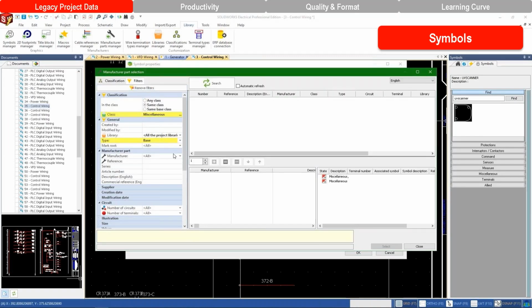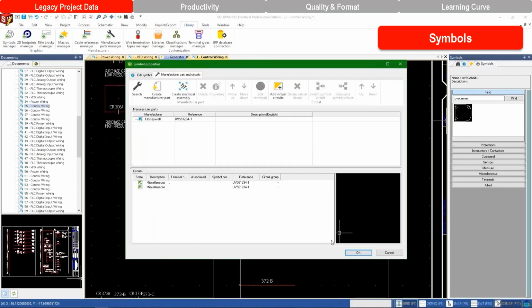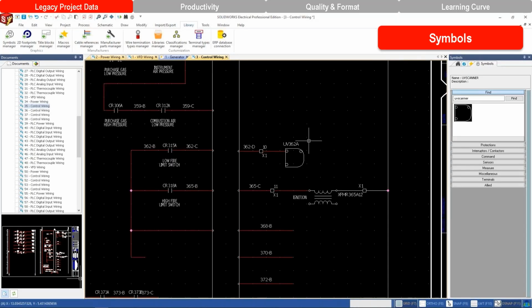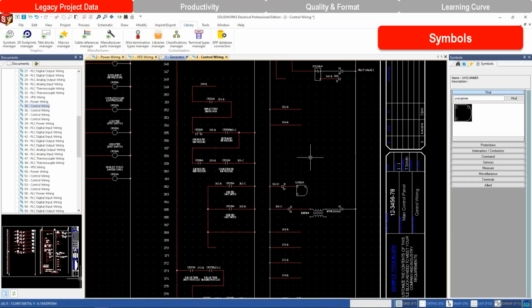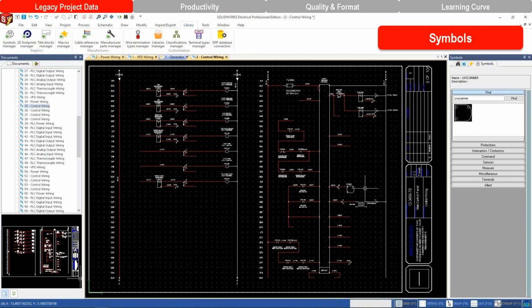What I'm quickly previewing here is the ability to add manufacturer's parts onto this. You guys saw me do the workflow from simple import, convert it, change those attributes. But now, what you're witnessing is the power: this guy is fully ready to go and be utilized within the application, carrying all the necessary connection points and metadata to ensure our BOM is accurate and all of our wire data is accurate as well. Just to reiterate, everything we're looking at inside of here is fully converted from AutoCAD, in this case, AutoCAD Electrical. So you can kind of see the level of conversion that we get.